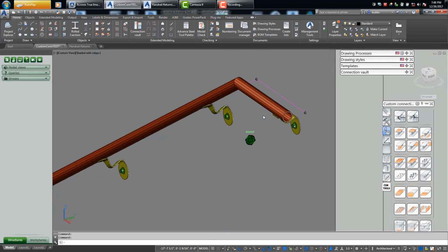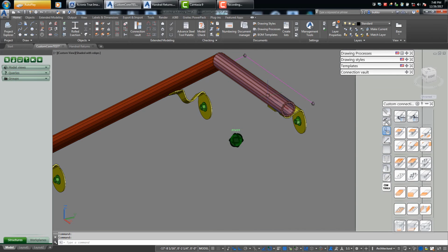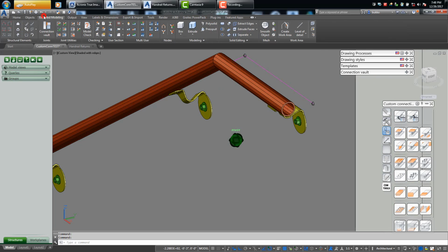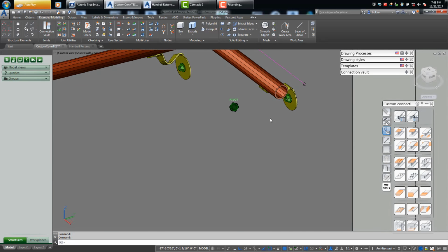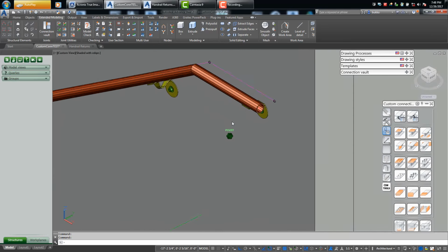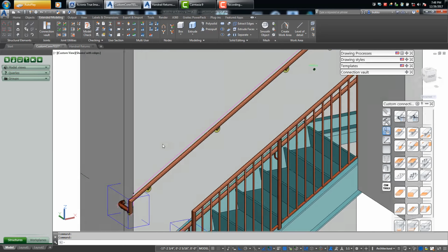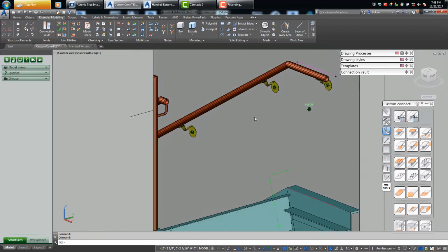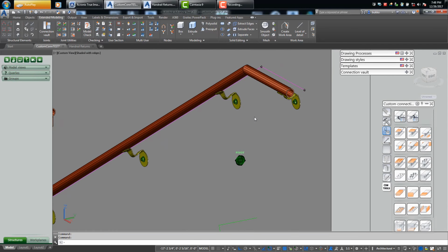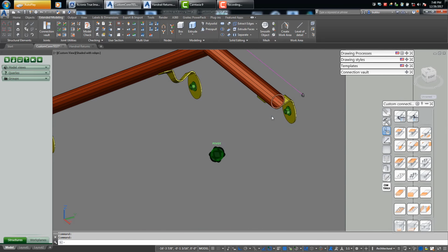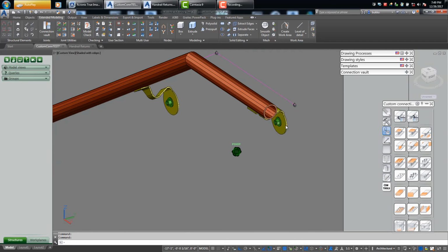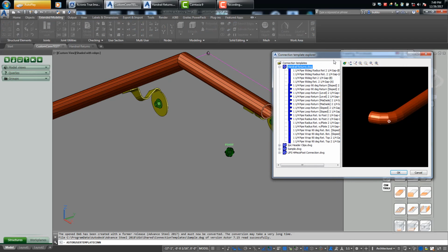if you want to return, I've noticed that I've tried to model the Grabrail, the new Grabrail macro. I think it's right up here, and it doesn't like any kind of short return. It'll get fouled up. So basically, you have to model these things with straight lines, and it's still a great macro. I mean, compared to nothing, that's for sure. I mean, they just introduced this recently. But if you want to create a return here, you're going to have to create a custom component that you can work with quickly. So these first two are my first attempt at that.